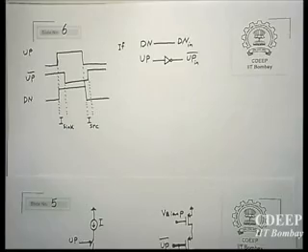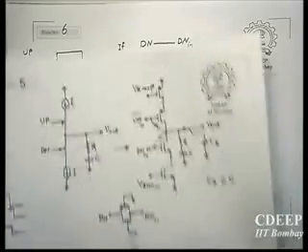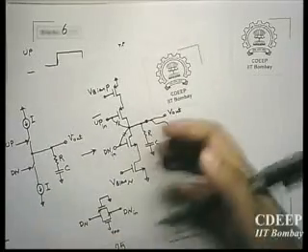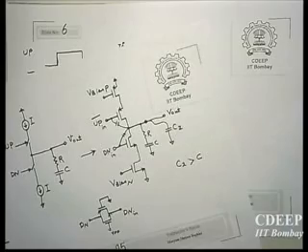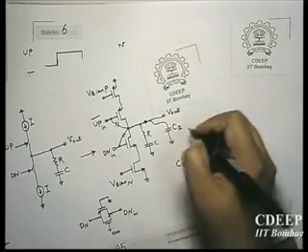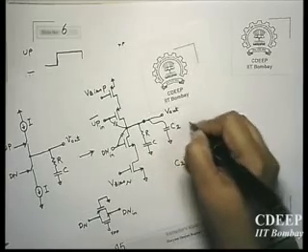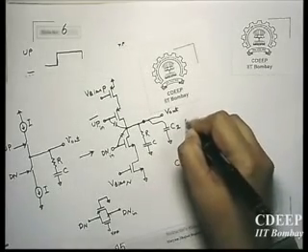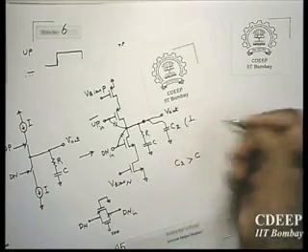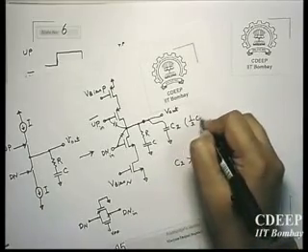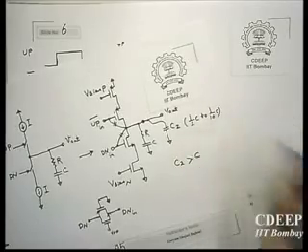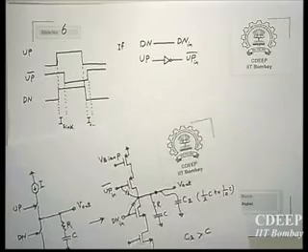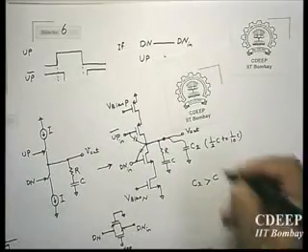Okay, what are other problems? Here I wanted to say the impedance of C2 to be around 2 times to 10 times. I said C2, so the impedance of C2. So C2, for example, can be half of C to 1/10 of C. Half of C also is a little large. It's better to be less than that.